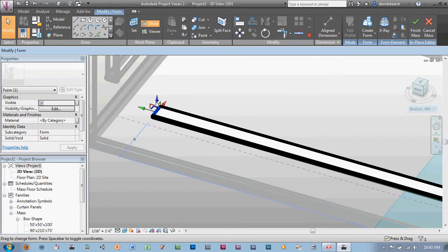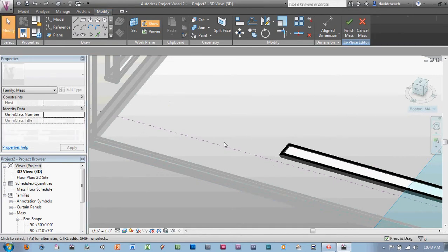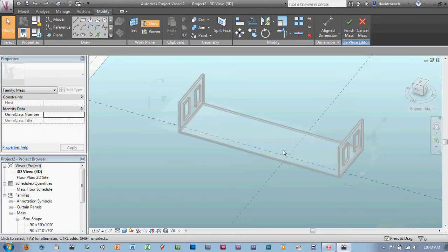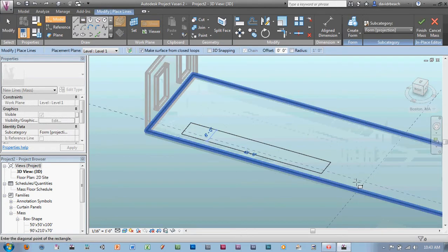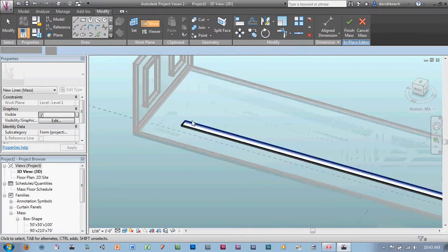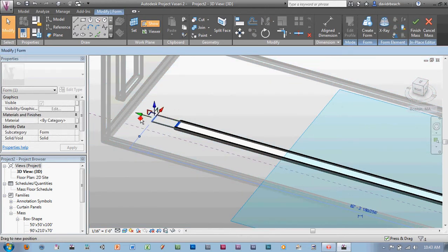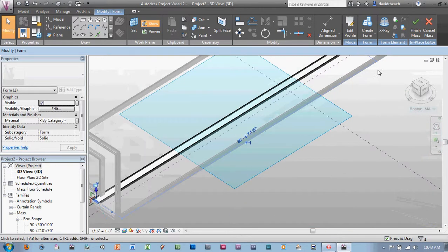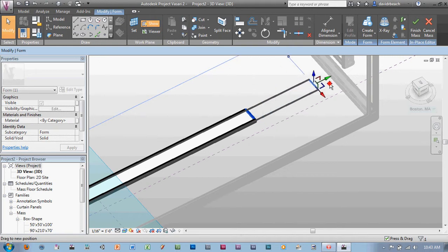Now if you notice how it free moved that time, I had actually selected the wrong location in the grip. I did one too many undos. Let me start again here. Create a box. I'm going to select that surface. I want to make sure I'm grabbing just that green arrow, so anywhere I move the mouse, it should only move around that axis. That keeps me working with a higher level of precision. Do the same thing here. It should snap to the edge.